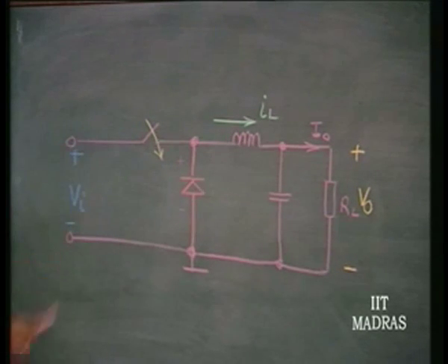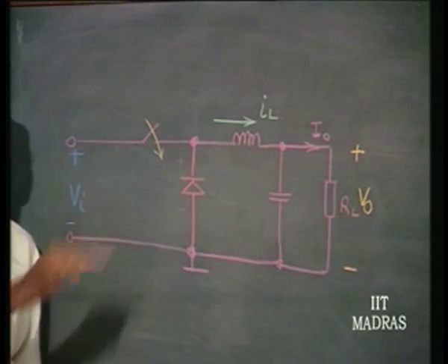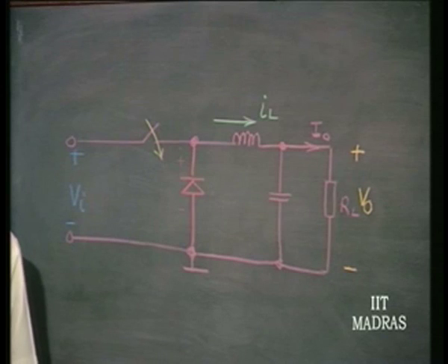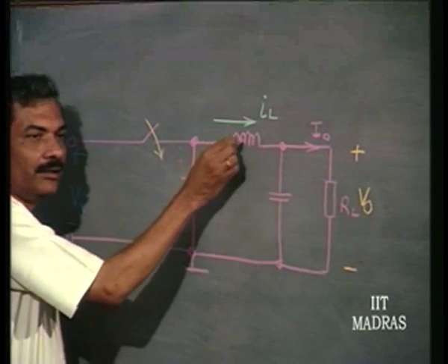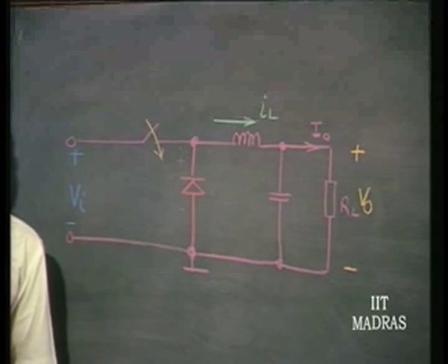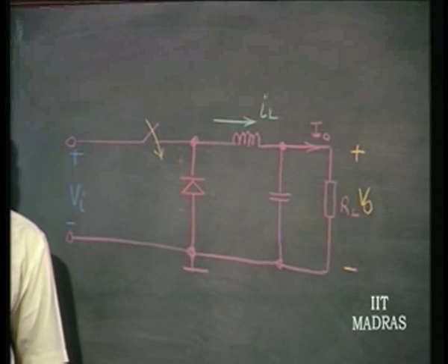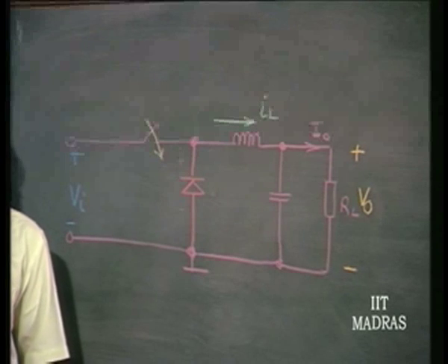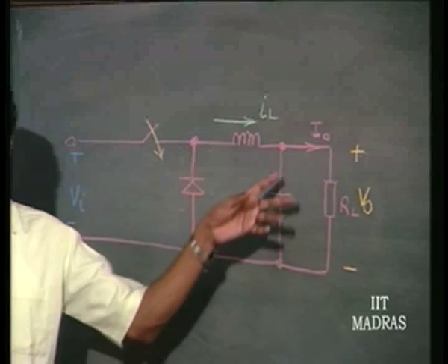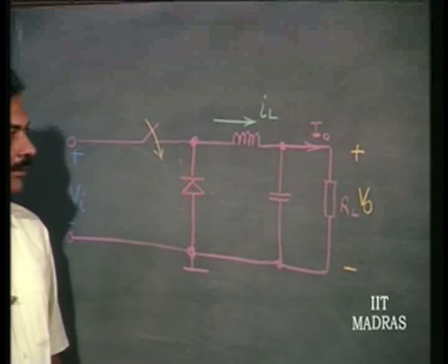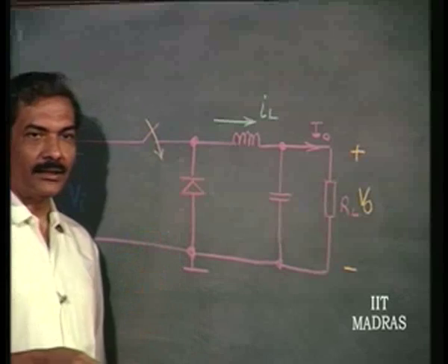So, the entire converter has the following components now: a switch, which is obviously a transistor switch, and a diode, which is a power diode now, because it has to carry the load current anyway, right. So, the inductor, again the inductor also has to be designed to carry the load current, okay, and a capacitor rated for that voltage, whatever voltage. Okay. So, these are the things that are necessary.